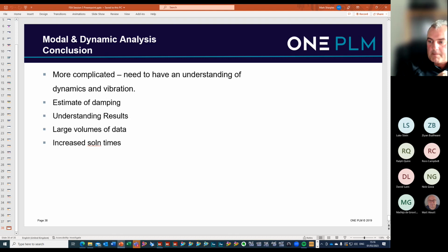But you can do material damping, can you, within this solution as well? That works off the material properties? Yeah, you can get it to calculate from the material property. You can have material or geometric damping. You can apply whatever you want to apply into it. You can also do stress stiffening, so you can have it where the more the cycles, the parameters will change as well.